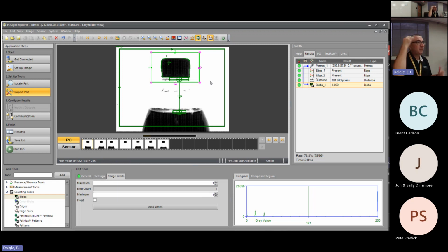So if the camera sends a bad result and I want to use that bad result to have a pneumatic cylinder reject something off the line, bam, I can use that inspection result as an input to the PLC. That's a huge, huge deal. You use it like any other sensor. Okay, so that part and executive action is knock it out of the conveyor. You got it.